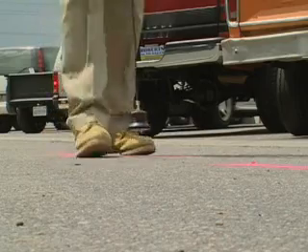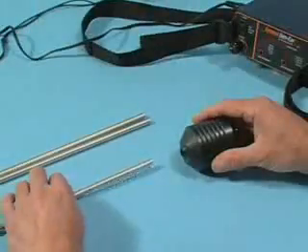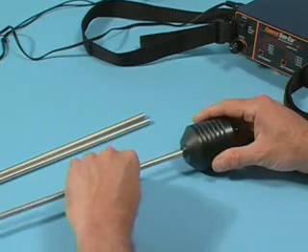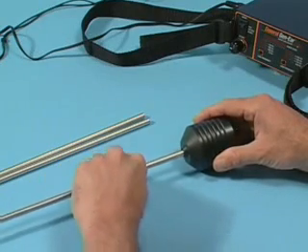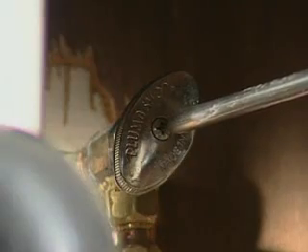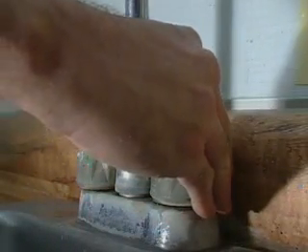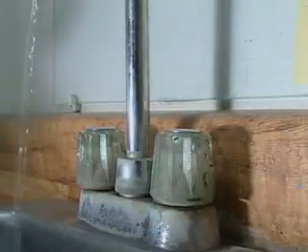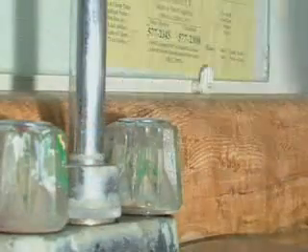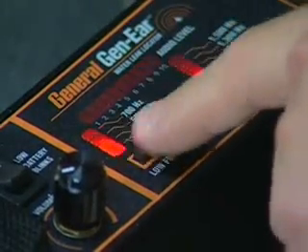But before you can locate a water leak, you've got to know what you're listening for. Here's a tip for beginners. Set up the Gen-Air with the probe sensor and probe bar. Touch the tip of the probe bar to the water line under a sink. Then barely turn on the faucet so the water is dribbling out. This simulates the sound of a leak. Turn the faucet on and off and try all frequency combinations until you hear the difference.